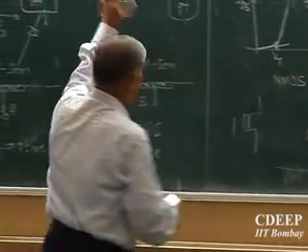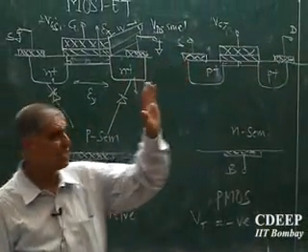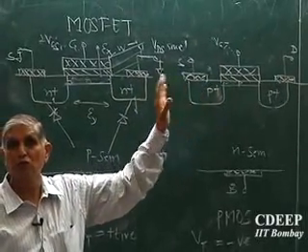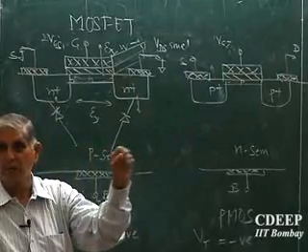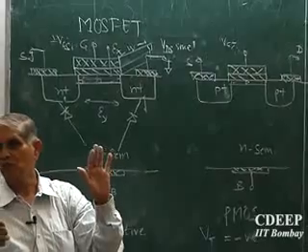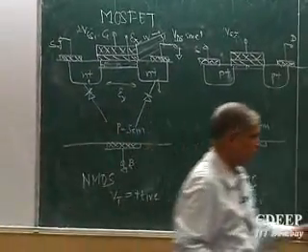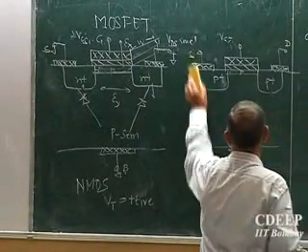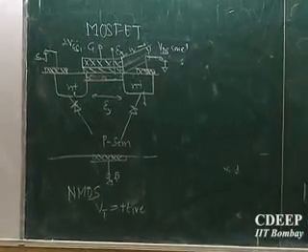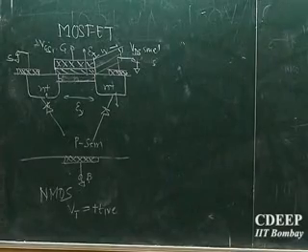Okay. So are these figures clear to every one of you? The depletion transistors have prefabricated N or P regions. Prefabricated means during fabrication there is a layer created by us. Is that correct? In enhancement mode, it's only the substrate which is kept there. Is that correct? Okay, so these interesting points we have finished. So let's do some transistors now. We'll only use N-channel devices for representation. Anything which I do for N-channel with opposite polarity is valid for P channels.